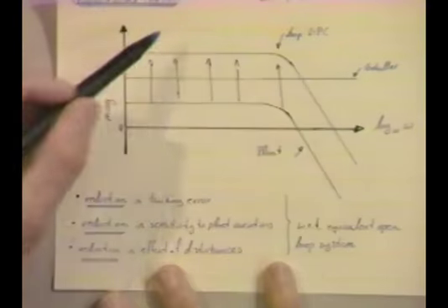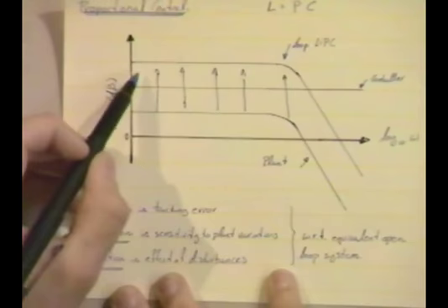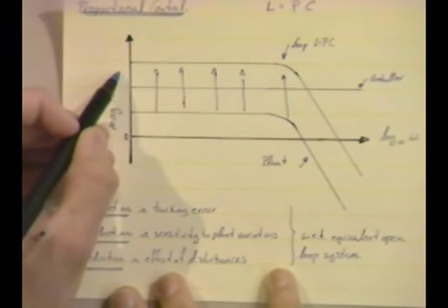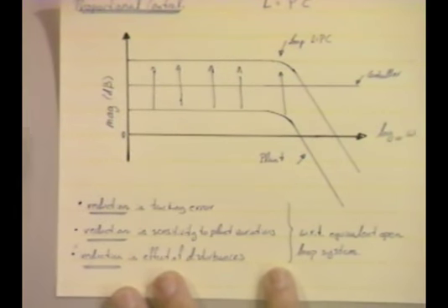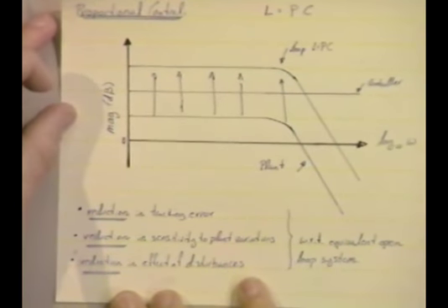You'll go possibly maybe at 38, depending on the details. But you won't stay at 40 miles an hour as you slope up using proportional control. The reason being that the sensitivity at DC, despite being small, is not 0. For proportional control, in other words, when you look at the product of PC in the low frequency limit, it's not infinity. It may be large, but it's not infinite.